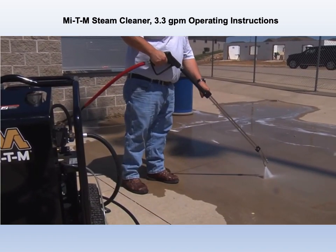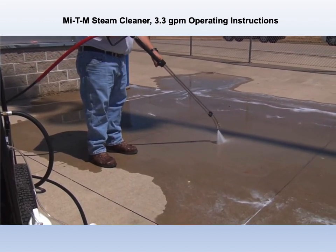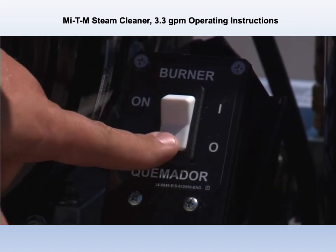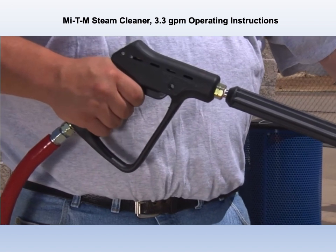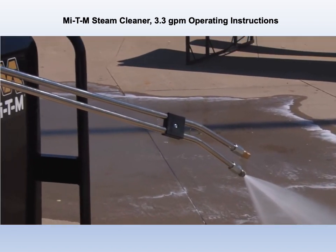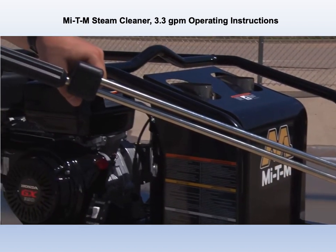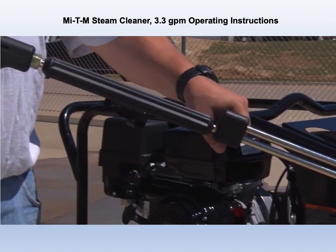When your project is complete, take time to cool down the coil of your pressure washer. Turn the burner off and squeeze the trigger for approximately 1 minute, or until the metal lance feels cool to the touch. Heated water pulls the metals out of hard water and allows them to collect on the coils, so cooling the coil is very important.